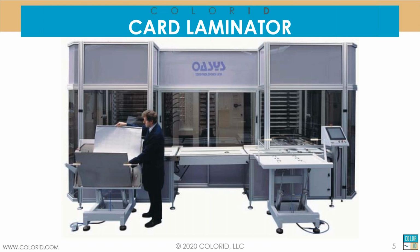Those sheets are laid together between highly polished sheets of steel or some kind of sturdy metal, kind of like cookie sheets, and that's what this technician is doing right here. He's layering the sheets between the platens, and then he will pick up the assembled group and insert them into the slots behind, which are an oven, and they will be subjected to heat and pressure over a period of hours, and then cooling, so that the layers of the card are all fused together.